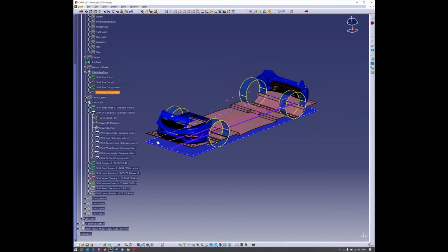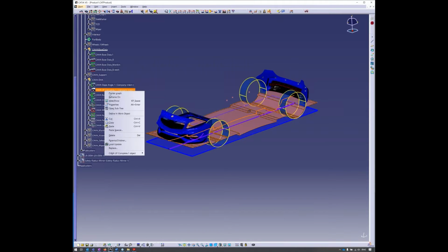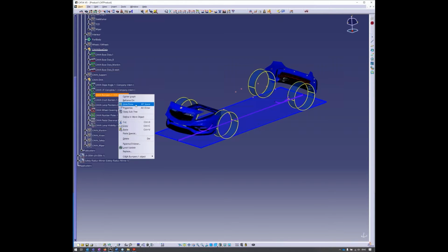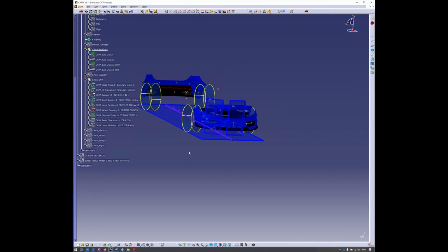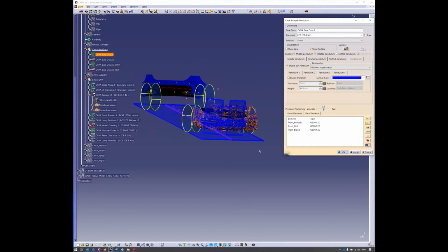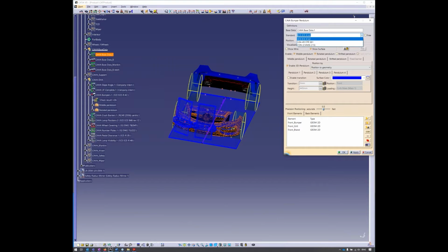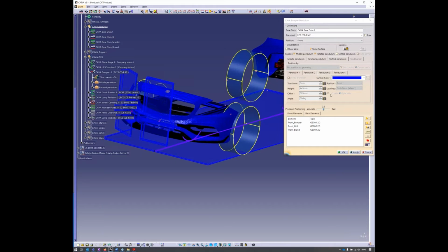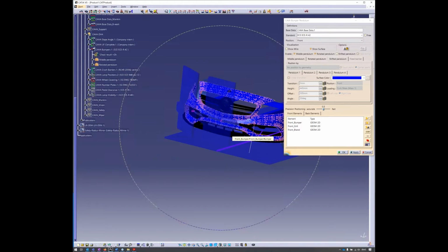Another area we have is crash barriers or bumpers. So it's possible to assess some damage or to assess where the contact areas of your impactors will appear on your vehicle. So for example, the check for the low-speed bumper crash tests according to ECE R42, or also the comparable US regulations. It's possible to define the pendulum for the impacts. You have several options for the middle pendulum, for the rotated pendulum, and also for the non-centric pendulum impact, the shifted pendulum. And for each of these pendulums, you can calculate the impacts in 2 different loadings as required by the regulation.